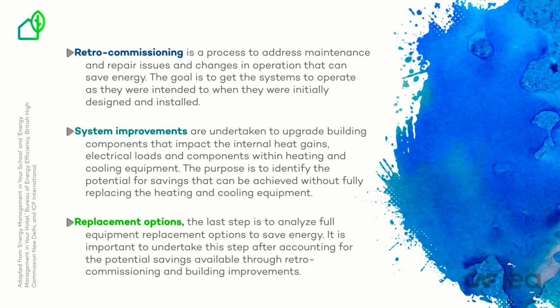The purpose is to identify the potential for savings that can be achieved without fully replacing the heating and cooling equipment. Instead, the focus is on replacing components that impact overall energy efficiency. The other goal of this step is to reduce the heat gain in the buildings by increasing the efficiency of lighting, appliances, and other equipment, which will help reduce the size of the cooling equipment needed when looking at equipment replacement options. And thirdly, replacement options.